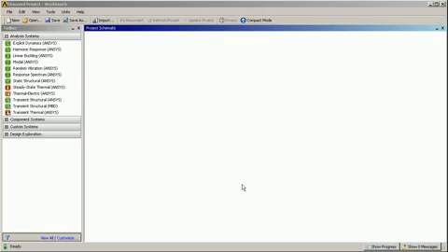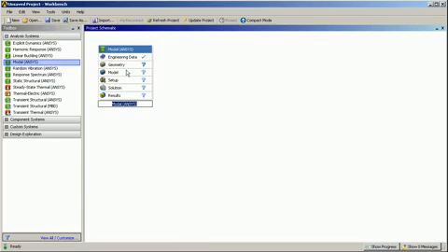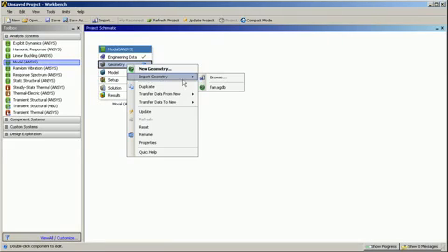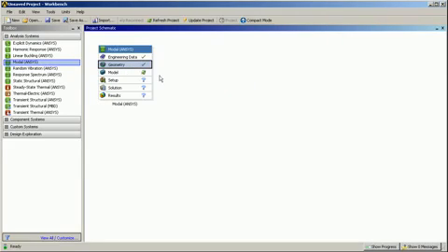Today we'll be using the mechanical simulation available in release 12.1 to solve the linear vibrations of a simple house fan. Let's start by dropping in a modal system into the ANSYS Workbench project schematic and then searching for the geometry of the fan. So I've selected that. Now let's open up the geometry model inside the mechanical simulation application.